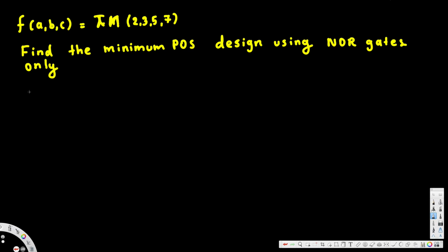Now let's look at the truth table. If you look at the truth table, you will know what this represents. Here we have three variables, A, B, C. Three variables mean 2 power 3, so we are going to have 8 different orientations. It's going to go like this: 0, 1, 0, 1, 0, 1, 0, 1, and then 0, 0, 1, 1, 0, 0, 1, 1, and the last one is going to be 0, 0, 0, 0, 1, 1, 1, 1. Okay, this is going to be the orientation, right?